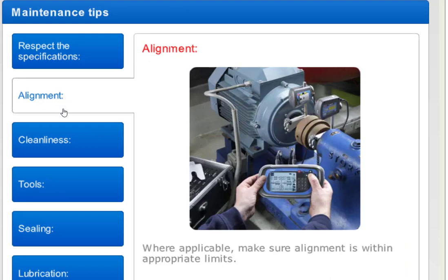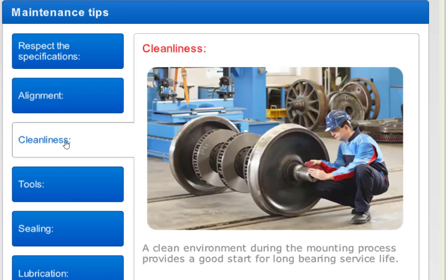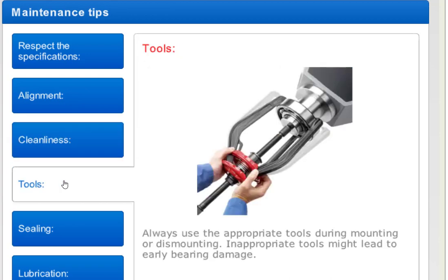Where applicable, make sure that alignment is within appropriate limits. A clean environment during the mounting process provides a good start for long bearing service life. Always use the appropriate tools during mounting or dismounting. Inappropriate tools might lead to early bearing damage.